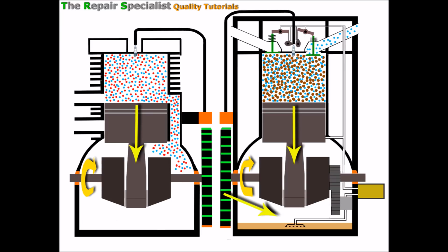And that's quite different to the four-stroke engine. The only means of lubrication in the four-stroke is by use of this oil down here in the oil reservoir in the sump area, because no lubricating oil whatsoever is coming in with the fuel on a four-stroke engine. It's just the fuel itself. So there are some big differences between the two there.